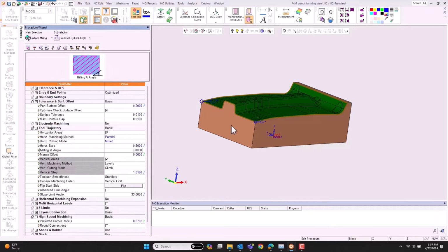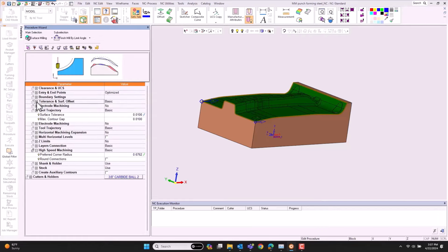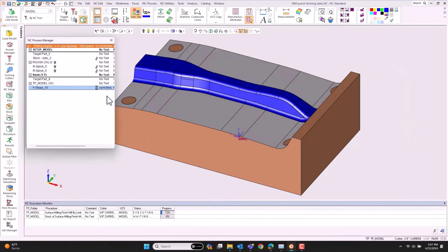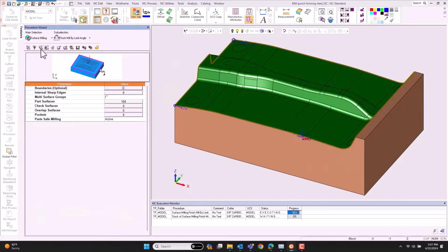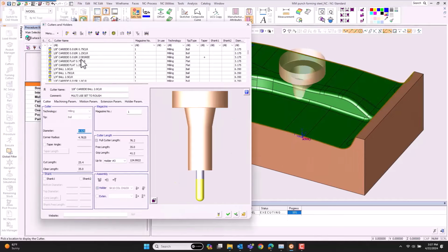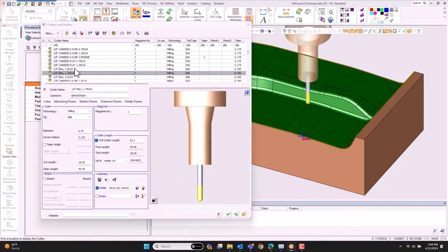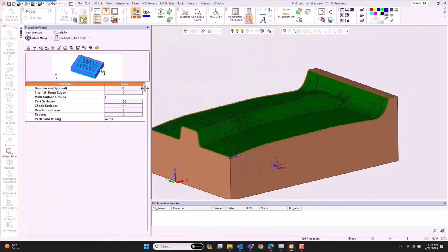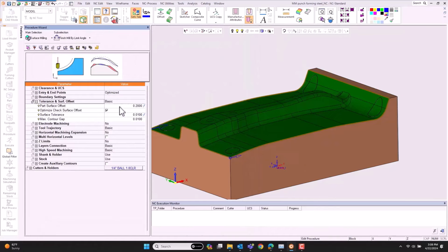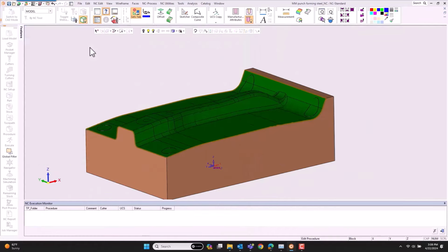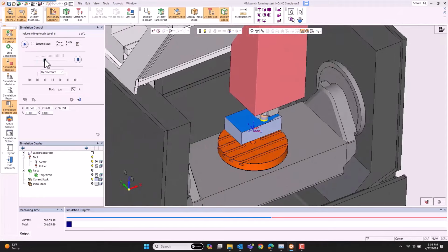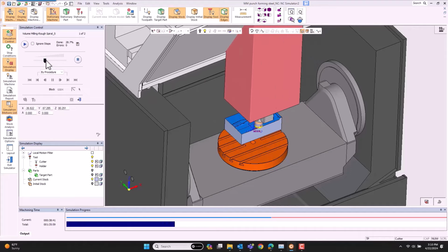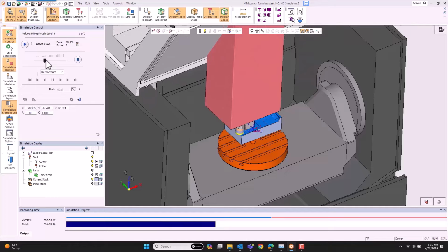Here we're doing a finish by limit angle. So as it creeps around, like 45 degrees along a fillet, it can transition how it goes about cutting it. So maybe it lace cuts the top flats, but then Z levels those taller sidewalls. Each of these can be controlled too with the size of the tool length. So perhaps I'm starting with a shorter cutter because I want to have more rigidity and I can cut quicker. But then as I get into longer areas, it won't reach. So the system knows enough to then change over to the longer tool that happens to have a different speed and feed. All of this, of course, can be simulated.